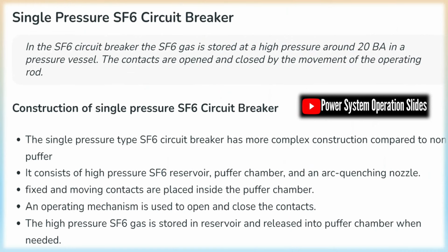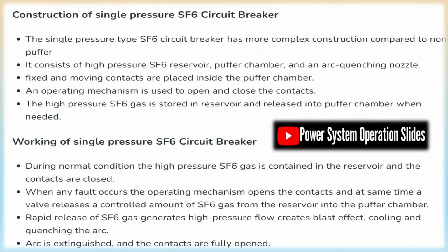SF6 circuit breaker types. At present, SF6 circuit breakers can be classified into two major categories: dead tank enclosure at ground potential, and live tank enclosure at line potential. Dead tank designs can offer greater short-circuit current breaking capability and seismic rating, but are relatively bulky and require more SF6 gas, whereas live tank designs are modular and more compact.